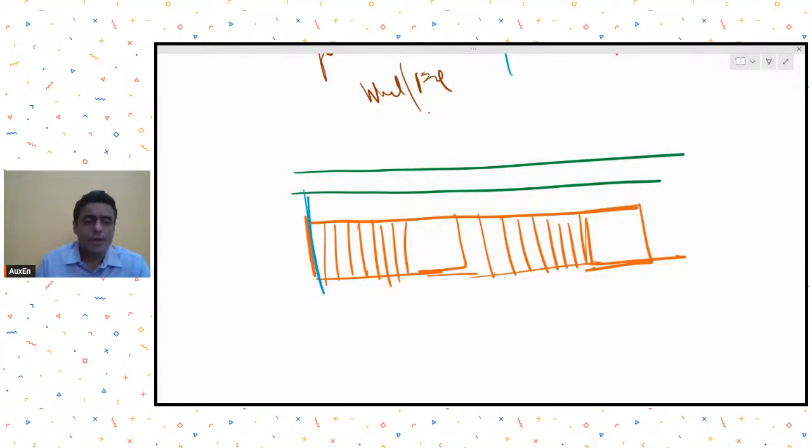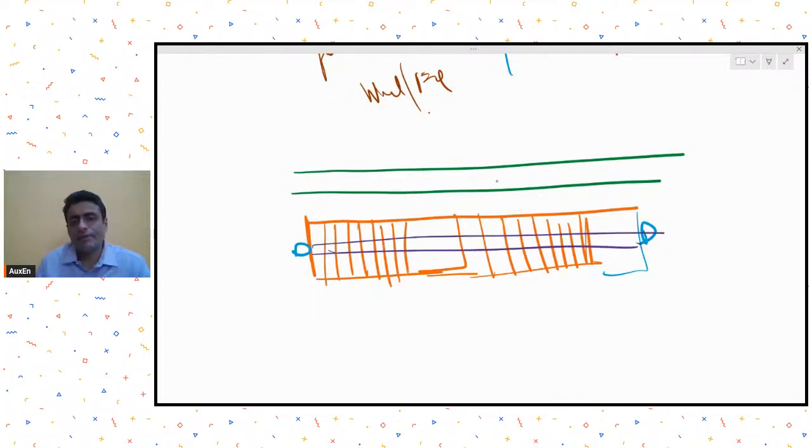Again, you need to plan your supports. Maybe your supports can come in the form of a column, and then you can have a beam attached over here, whatever it is. Or you may take a single column like this, and have a stringer beam like this, and then take these steps cantilevering out from the stringer beam.